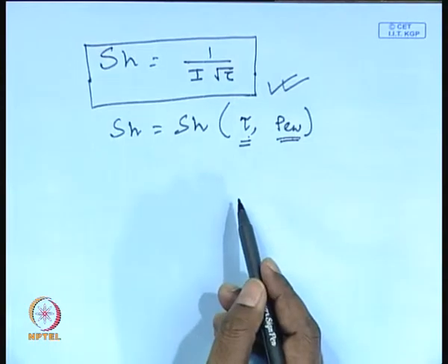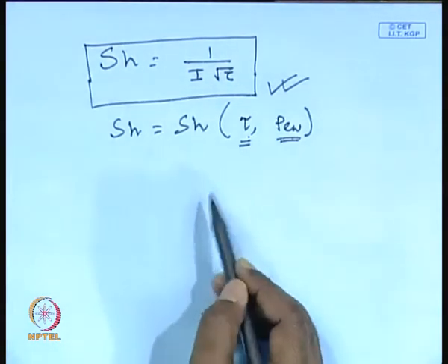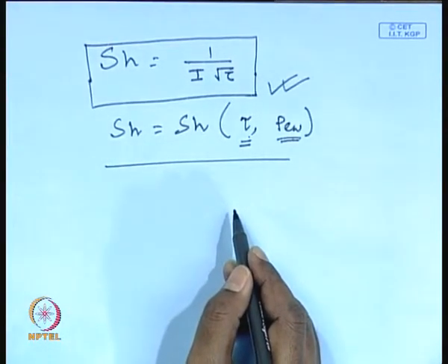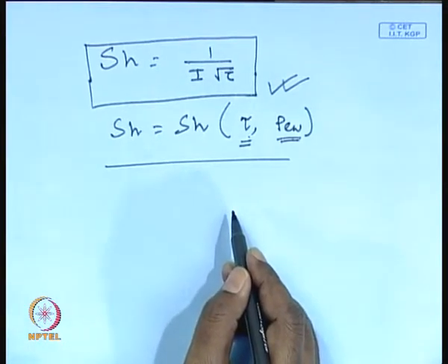There is a non-dimensional version of mass transfer coefficient. So, as time progresses, the concentration boundary layer develops on the membrane surface. Physically it means it offers more resistance against the solvent flux, and the amount of mass transfer will be reduced. Since the amount of mass transfer will be reduced by the mass transfer coefficient, and the permeate flux is connected by the boundary condition at y equal to 0, if you remember, the permeate flux will also decrease as time progresses. So, this may be of interest to chemical engineers to design a system efficiently.